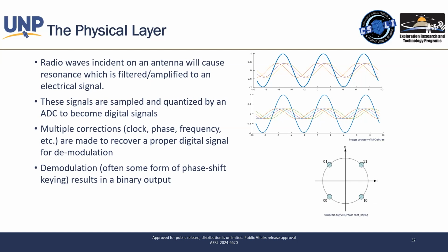So this is the fundamental concept behind phase shift keying, that you can break a wave into multiple phases, right? But you're going to take a penalty. In fact, if you have waves that are too small, if you're transmitting over noise, the noise is just going to drown that out, right? And so there's sort of a trade-off between choosing how many phases I'm going to embed in my signal versus my ability to pull that information out from those phases. Those are all things you need to take into account.